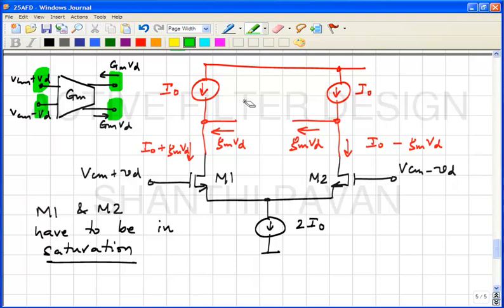When the drains are shorted to a voltage source, then it can be tried also. As long as we said that the drains of, in the earlier example, we said that the drains of M1 and M2 are connected to a supply voltage which is sufficiently high to maintain M1 and M2 in saturation. I thought you said it doesn't matter. No, it does not.